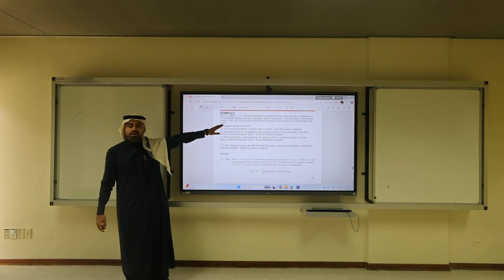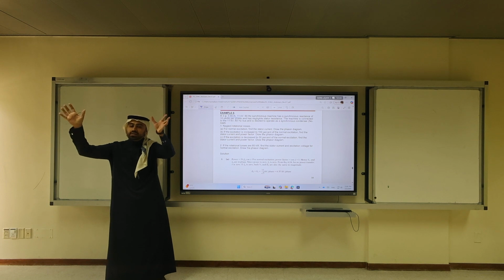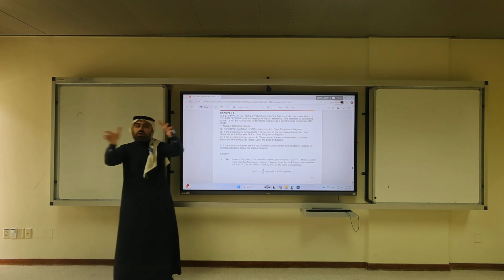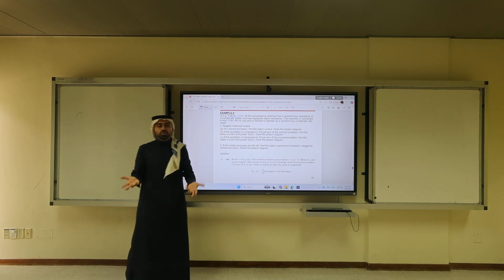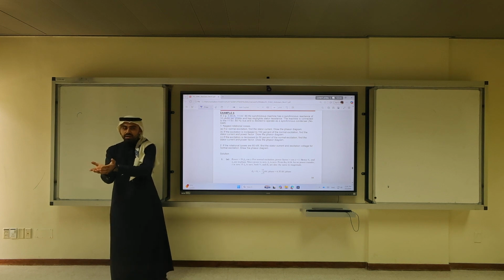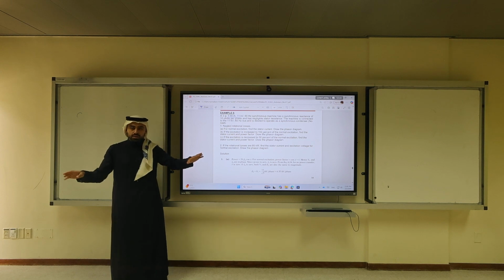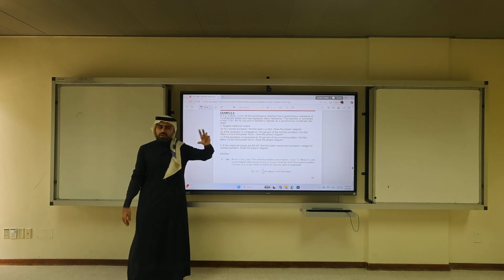No, that's too much. So now you can understand that the generator in the power plant can be changed to work as a condenser. But what is the cost? Who's gonna pay the price? The exciter engineer, the engineer who's taking care of the exciter and controlling the field, is gonna have to really focus and be careful not to ruin the grid. Nowadays there is a control mechanism to control it. You have to be careful not to ruin the power factor of your system.